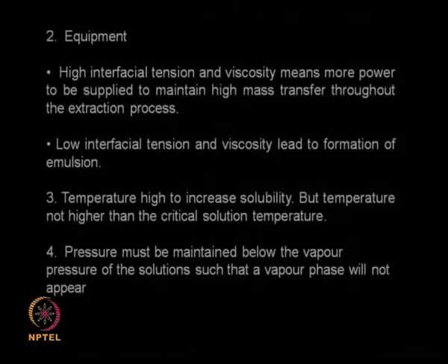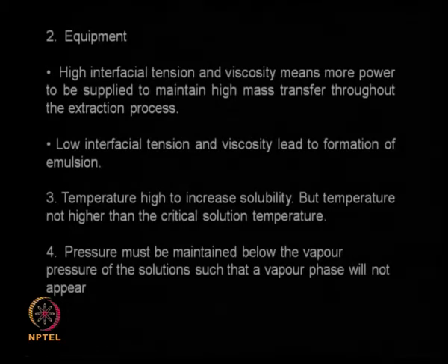Now, let us look at equipment. If the interfacial tension and viscosity are high, obviously I need to put in more power to achieve good mass transfer. If I am mixing two phases and the viscosity is high, I will have an agitator, and the agitator has to revolve faster. So, the power required also goes up.